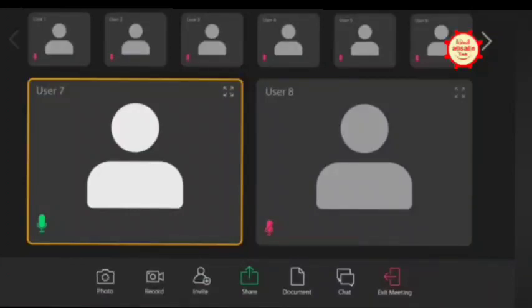But recently, I think they have included transportation vessels in PV Elite, no? You can analyze transportation vessels in PV Elite as well. Those are the loads; while transporting, if we need to design saddles, we can give those loads in PV Elite. But in PV Elite, they have not introduced the design of Section 12 transportation vessels.